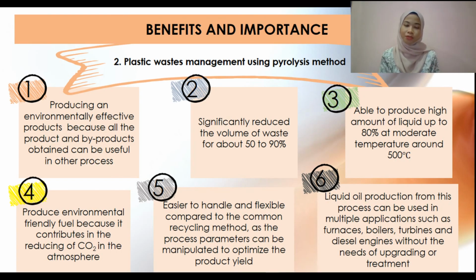Next, we will discuss the benefits and importance of plastic waste management using pyrolysis method. Firstly, it will produce environmentally effective products because all of these products and byproducts obtained can be useful in other processes. Second, it significantly reduces the volume of waste by 50 to 90%, and it is also able to produce a high amount of liquid, up to 80%, at moderate temperature around 500 degrees Celsius.